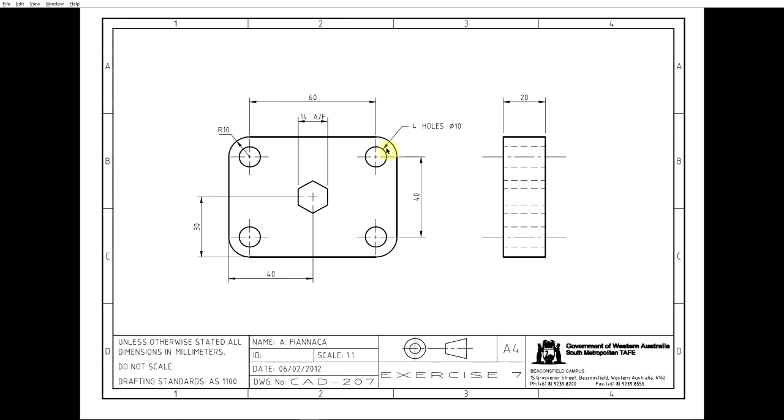In this case, what I'm going to get you to do is just using ortho, we're just going to project them straight across, so we get nice straight lines, and we're only going to do half of it because you'll see the bottom half is the same. And we'll then use the trim tool to trim up all the bits and pieces. We'll scale up the center lines, apply the objects to their appropriate layers, and we'll go from there.